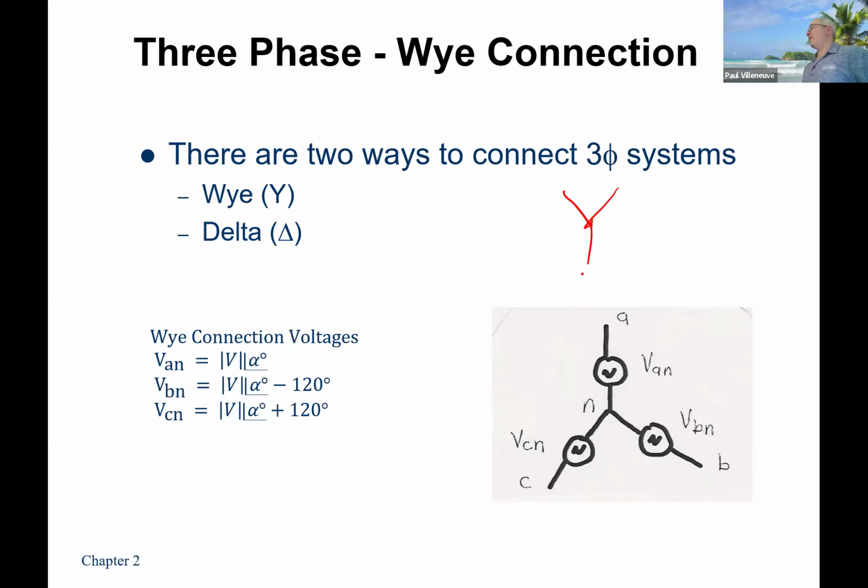But the way you connect them is you have a neutral, and all your individual power supplies are connected with the minus to the neutral and the plus away from the neutral. That's just the connection diagram. But each of those individual power supplies has to be internally configured so that they have the same magnitude and phase shift. That's why, when we talked about a generator, the windings are physically located on the machine so that you get an electrical 120-degree phase shift.